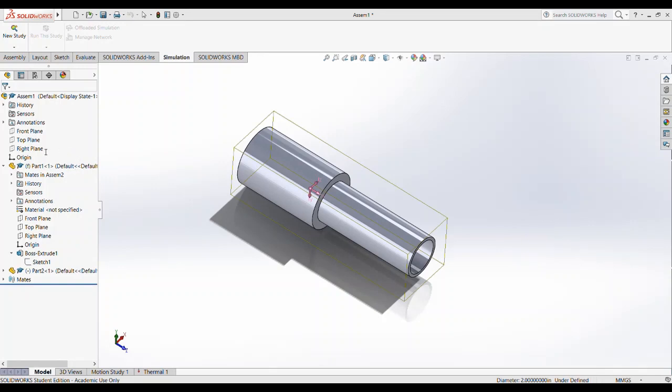And now it's telling me that this is 370.92 grams. I'm not sure if that's enough. I don't remember how many grams the other one was. So 455 grams is a pound, so this is about three-quarters of a pound, or a little bit heavier, for this whole system. The way you change the mass is you can make it thicker or thinner, or you can override mass properties here.